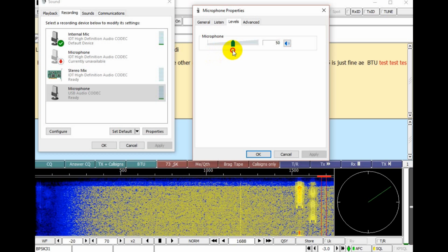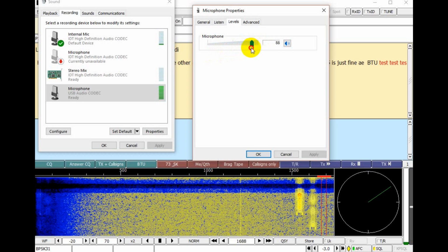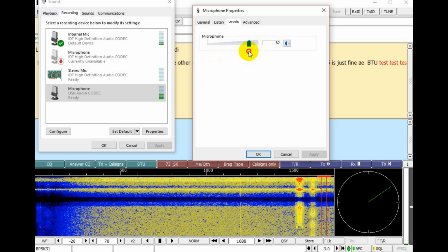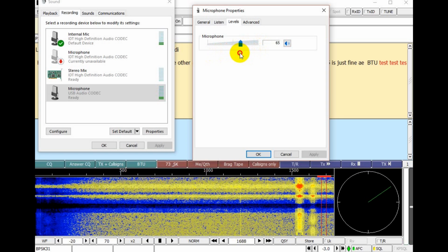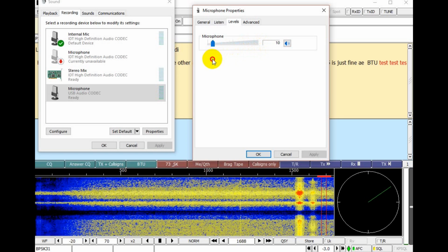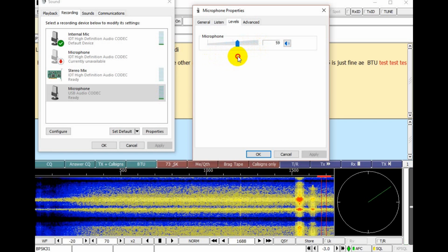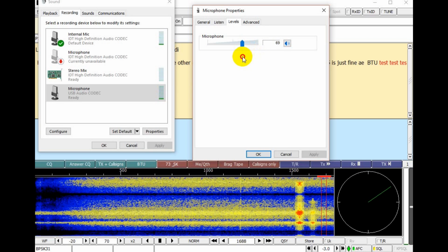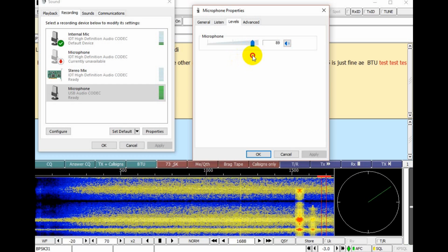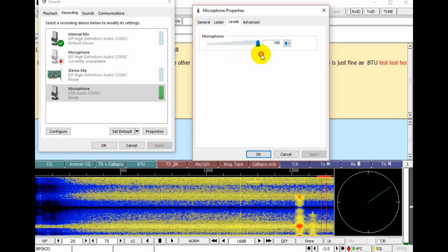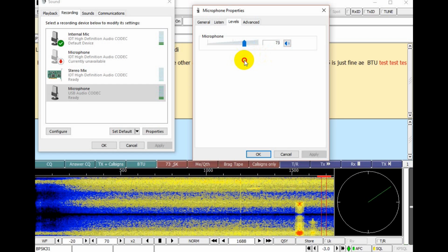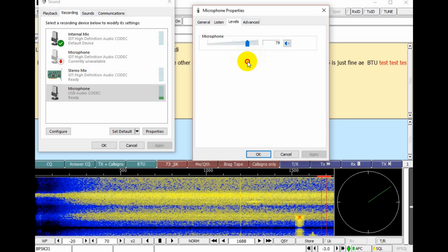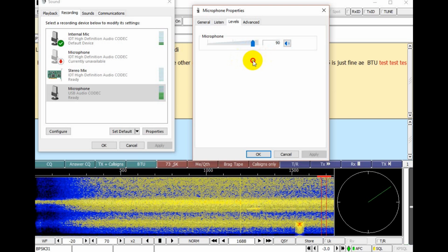Okay, now switch your radio to a live feed so that we have audio of PSK31 signals. Tune around 14.070 during the day and early evening, and 7.070 during the evening. You'll find that the waterfall will show signals. Fundamentally, blue on the waterfall indicates no signal, and the warmer the color is, the stronger the signal. So, adjust it so that you can easily see the signals. If the very strongest signals show a bit of red, back off just a bit, and you're adjusted about right.